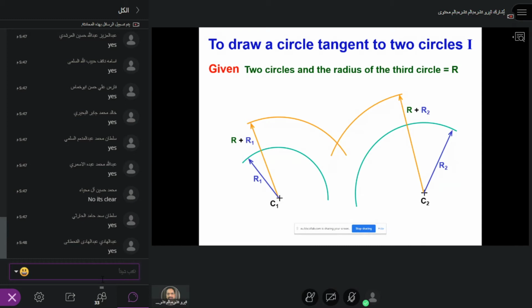You remember that last time we used the tri-square for something similar, and I think you can use a similar method. So the new point is C here. That's the center of the arc. Then you can join CC1 as the tangent, and then another one here for the starting point and ending point. Take C as the center, and any one of these as the radius. If you finish it, it's going to be a circle.